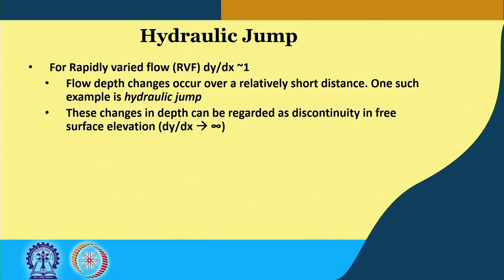So, these changes in depth can be regarded as a discontinuity in free surface elevation. So, dy by dx can go to infinity as well. If the depth changes rapidly over a small distance, it can be said that this is a sort of discontinuity in free surface elevation.